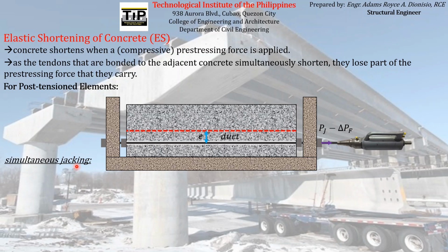Although the effect of the elastic shortening of concrete on the pre-stress force experienced by the pre-stressing reinforcement will only occur if the pre-stressing reinforcements are jacked sequentially.